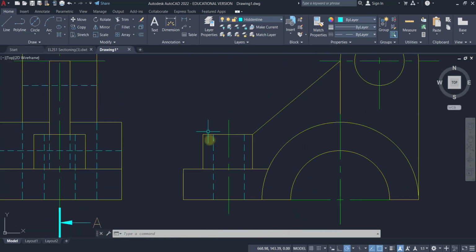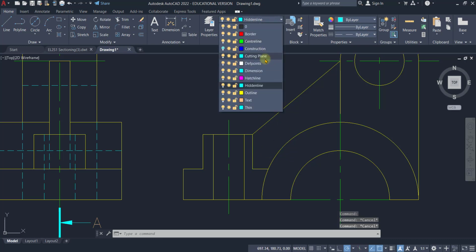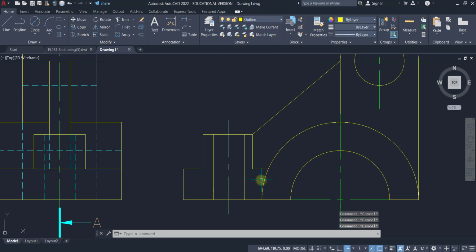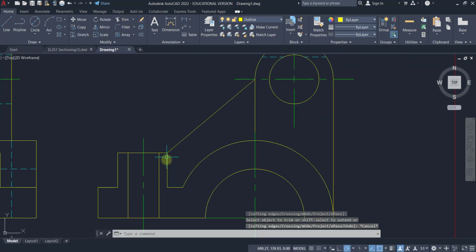And what is being exposed? I know that the hole is being exposed because you cut it open, so it's going to be a solid line. I know that this line here will have to be like this. It's opened up. I know that this one has to be here, so I need to add in, change to outline. I know that this semicircle outline here, I cannot see the entire semicircle fully. I need to trim this portion here, because this is a web.